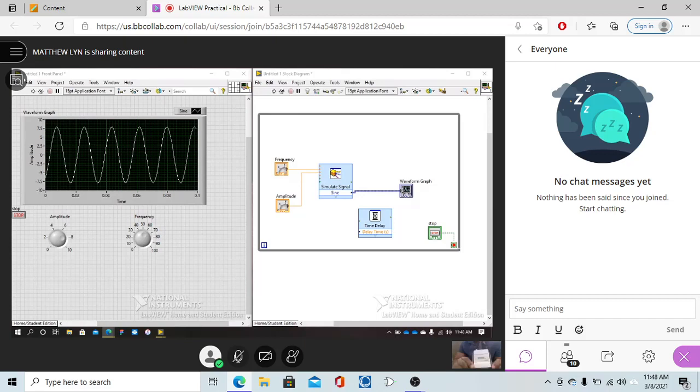So click the plus sign and then AI0. So this analog means input 0. Analog input 0, precisely. And then finish, right? Yeah, finish. It says now to change the minimum to 0 and the maximum to 5, and the acquisition mode to continuous. Continuous.